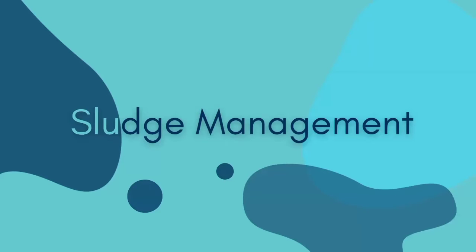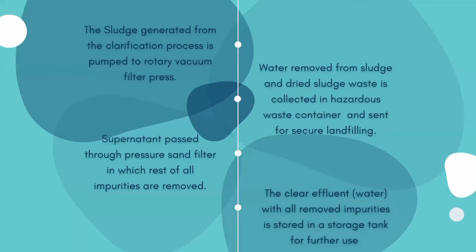Sludge management. So what is sludge? Sludge is a mixture of liquid and solid components, thick, soft, and muddy. It can be called a semi-solid sludgy mixture. Sludge generated from the clarification process is pumped to a rotary vacuum filter press. Water is removed from the sludge and the dried sludge waste is collected in a hazardous waste container and sent for secure landfilling. The supernatant is passed through a pressure sand filter in which the rest of the impurities are removed. The clear effluent with all impurities removed is stored in a storage tank for further use.